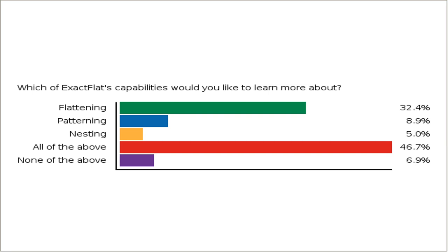The algorithms that we have are trying to do a couple things. Number one is we take a look at the energy within our pattern pieces, and if you can just think about taking a piece of cloth and stretching that cloth. When you stretch it, the cloth is going to want to behave like a spring and return to its original shape. When that happens, we say that there's energy in the cloth, and we're trying to get the energy to be zero so that we have a strain and sag-free piece.